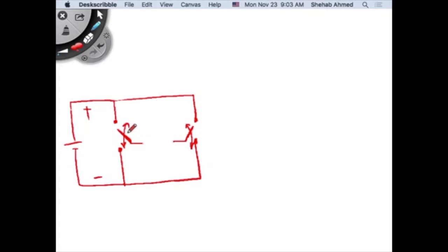The other thing is we always said that here across these switches, which I represented using this sort of arm with 2 contacts, across them, I always have a fixed, stiff voltage. Remember we said in the buck converter, the stiff voltage is the input voltage. In the boost converter, the stiff voltage is the output voltage. In the buck boost converter, that stiff voltage is the V input minus V output. Here, I have the same thing. I have a stiff voltage here that's always equal to this VDC, or the V input voltage.